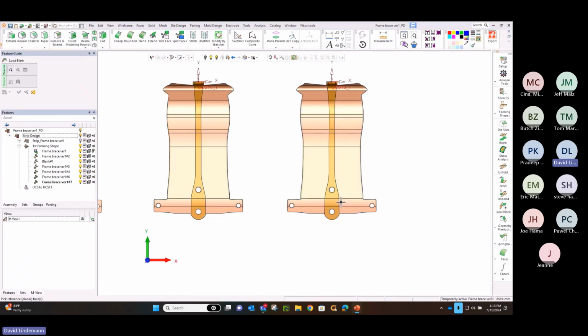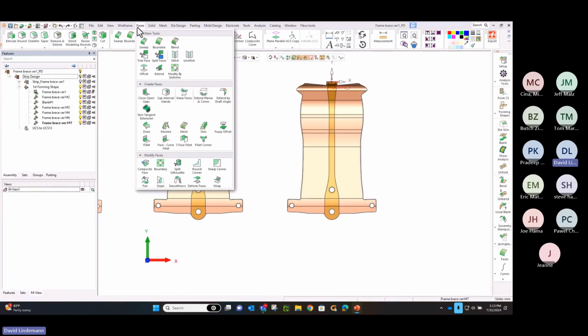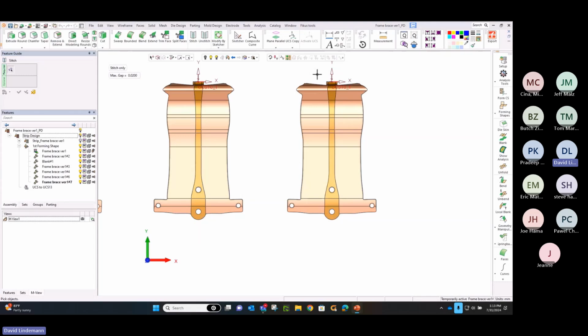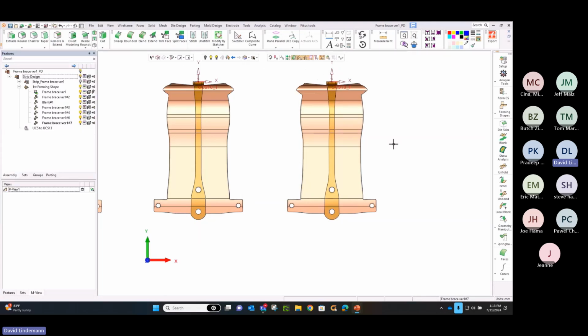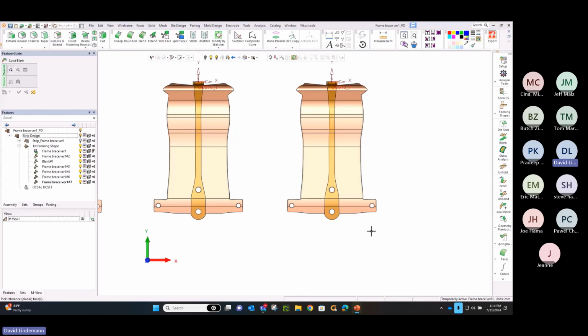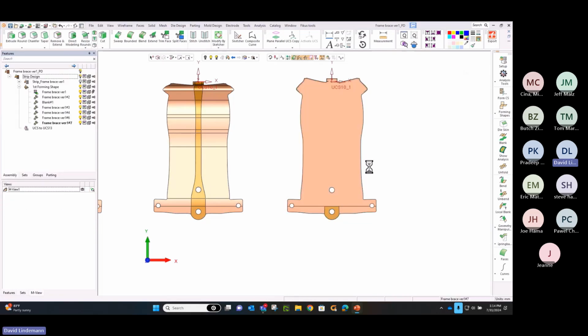And again, so many different tools for doing regular bending, like 90-degree bends where I need to maybe overbend. Maybe with that 90-degree bend, I'm going to crush the radius just a bit to take out some of the spring back. And again, you can check as you go with each of these what the result will look like. So there's the last one. There's my flattened blank for now.